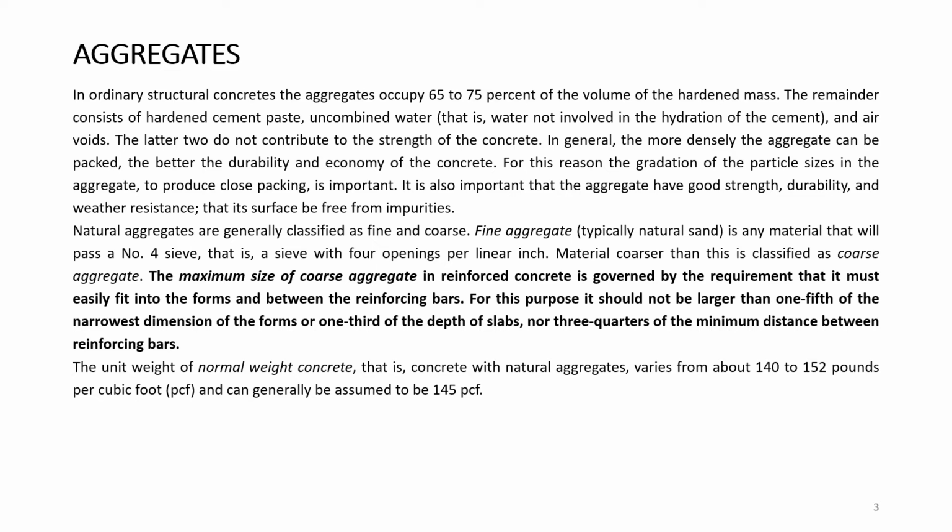In cement concrete, normally mass concrete will have a weight of 140 to 152 pounds per cubic foot. On the average, we take it as 145. This weight will be required when we calculate the weight of structures while going to the force system of the structure.